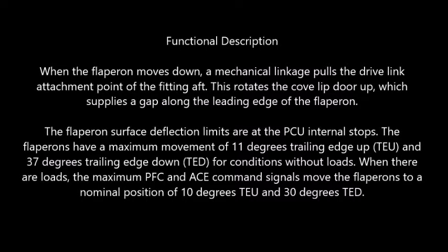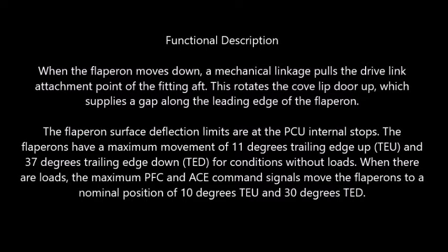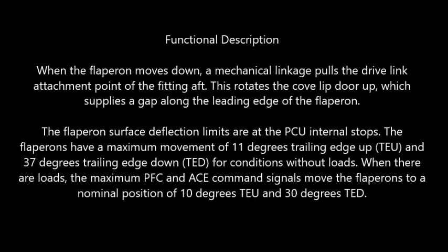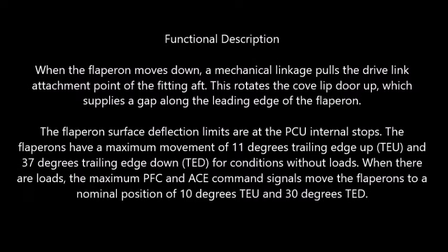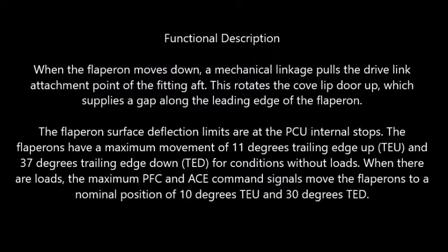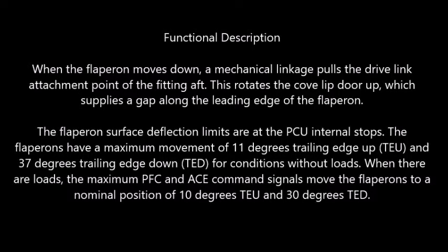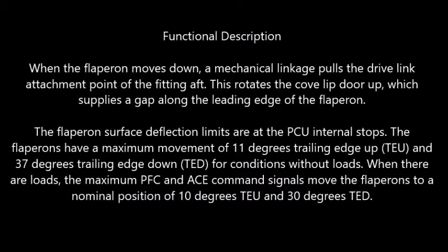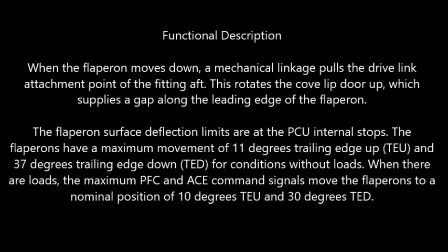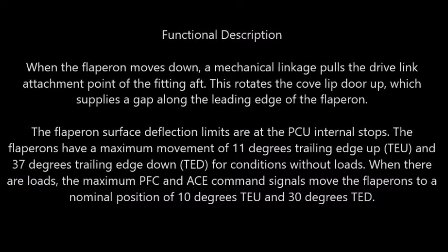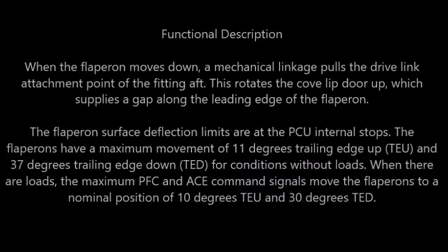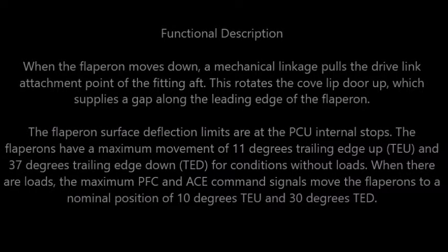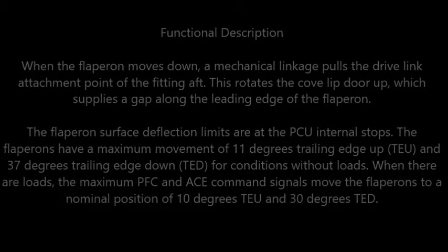The flaperons have a maximum movement of 11 degrees trailing edge up, TEU, and 37 degrees trailing edge down, TED, for conditions without loads. When there are loads, the maximum PFC and ACE command signal moves the flaperon to a nominal position of 10 degrees TEU and 30 degrees TED.